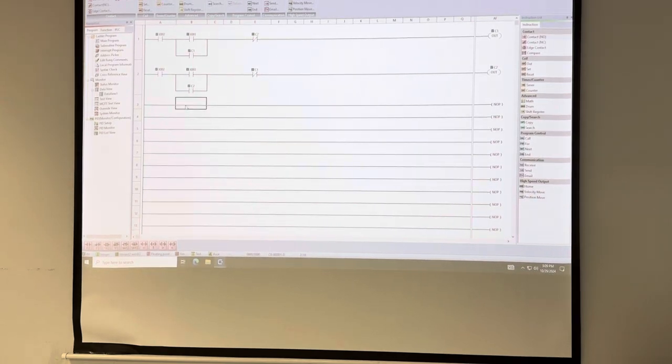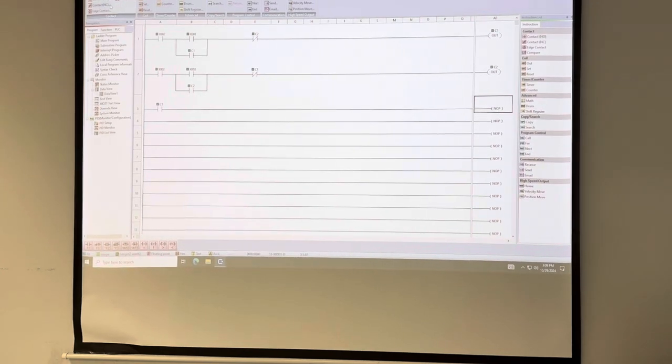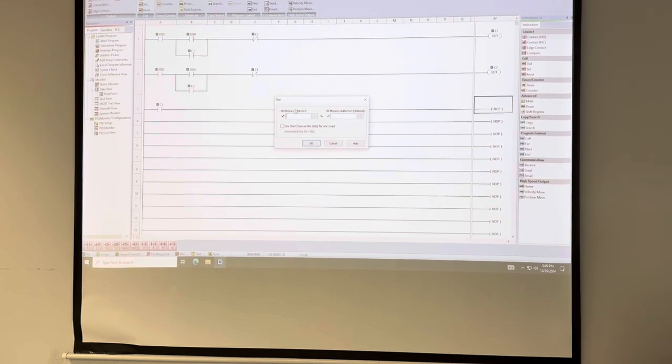And to visually look at this, so we are going to have C1 normally open, C001. Okay. When we come through, I will have an output here. I select an output, it will be letter Y001, which is the green one, the green light.